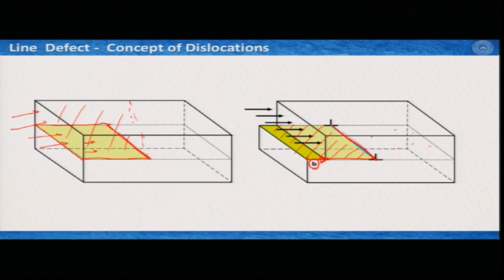Now, because the volume has to be constant, in this segment you might have some rearrangements of the atoms within the lattice, so that it can accommodate this unit vector displacement within itself. So, the atoms are arranged accordingly to accommodate the deformation, while the other part is not deformed or disturbed. This line is known as the dislocation line that separates the slipped and non-slipped part.